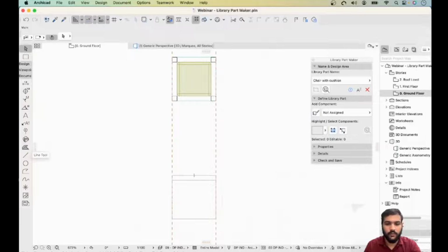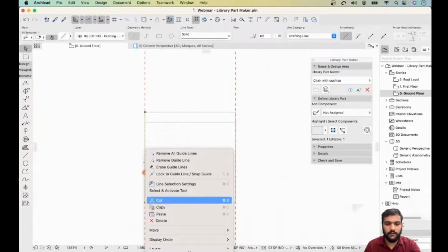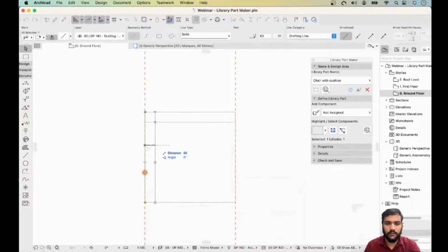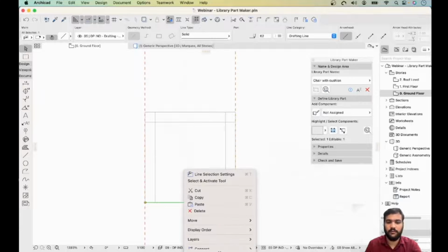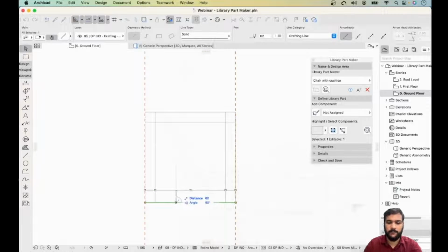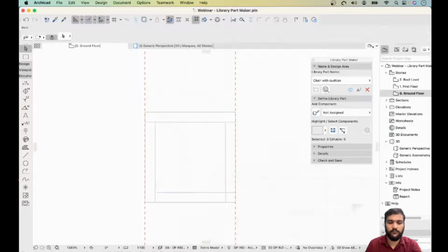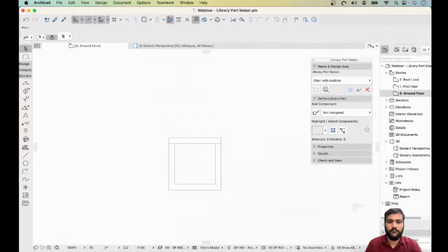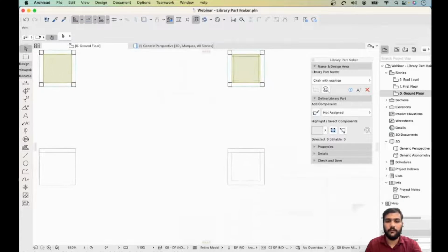And here as well, I will need to have, so you can just drag this by using command or control shift D. So it will be a shortcut for you to drag this. Okay, so I want to see the chair somewhat like this in detail.